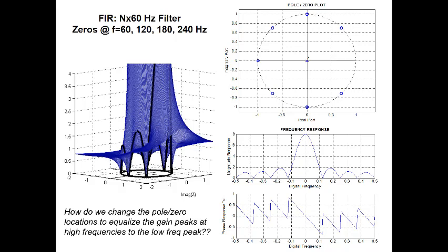Well, let's accept that. So I'm going to need to put some gain at higher frequencies and drop the gain at low frequency. Well, right now at low frequencies over here, these poles are pushing up the rubber sheet way high, and these zeros are dragging down the rubber sheet on the other side.